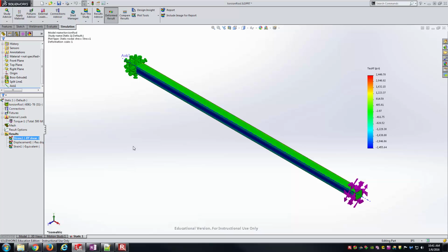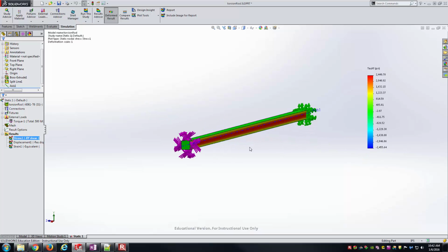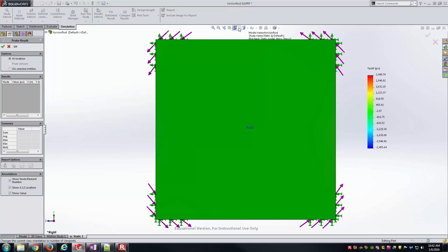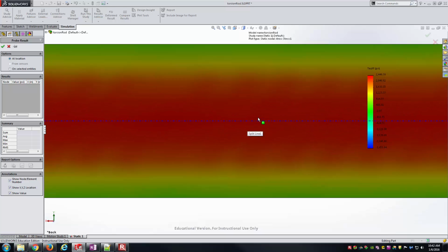And so you can see a lot different here. Probably the most noticeable thing is that the deformation scale, you have a much more realistic look of the model itself. And so here you can see the red side and the most positive numbers are very close to the blue side and most negative numbers here, which I would expect. And so we'll just investigate the positive side of it here. And for this specific example of a square cross section, the max shear stress should be located right at the middle of each of those side points. That's something that you'll find if you look in the Mott textbook there.